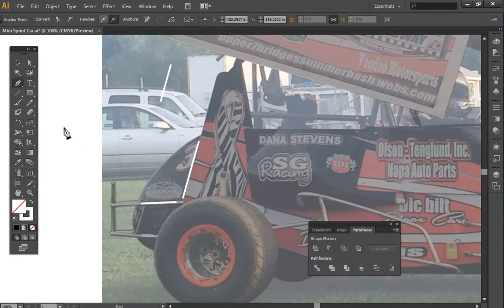create those single line cut paths, and you notice we're not trying to get the cut path so close to the outer outline that it's actually going to cut through. We want to leave sufficient spacing, and that's the reason I weight the lines at 0.0625. You look at the lines and how close they are to each other, and you can tell if something's going to overlap.